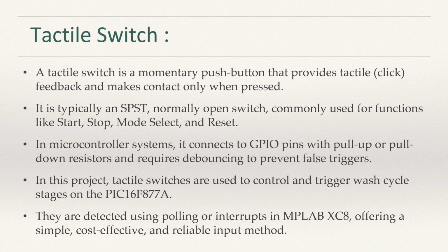Tactile switch. A tactile switch is a momentary push button that provides tactile feedback and makes contact only when pressed. It is typically an SPST normally open switch, commonly used for functions like start, stop, mode select, and reset. In microcontroller systems, it connects to GPIO pins with pull-up or pull-down resistors and requires debouncing to prevent false triggers.